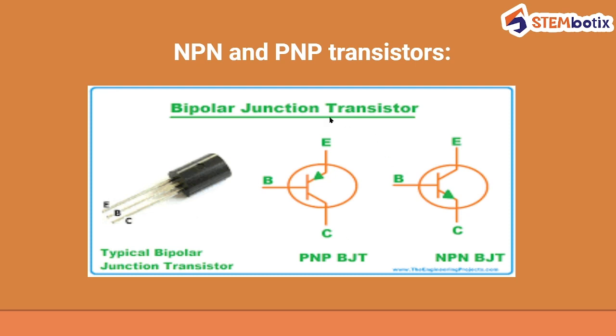In order to use a transistor as a switch, whenever you have connected your transistor with a light bulb and there is a battery, if there is no current through the base, meaning you have not provided a specific amount of current to the base of the transistor, then the light bulb connected to it will remain in the off condition.